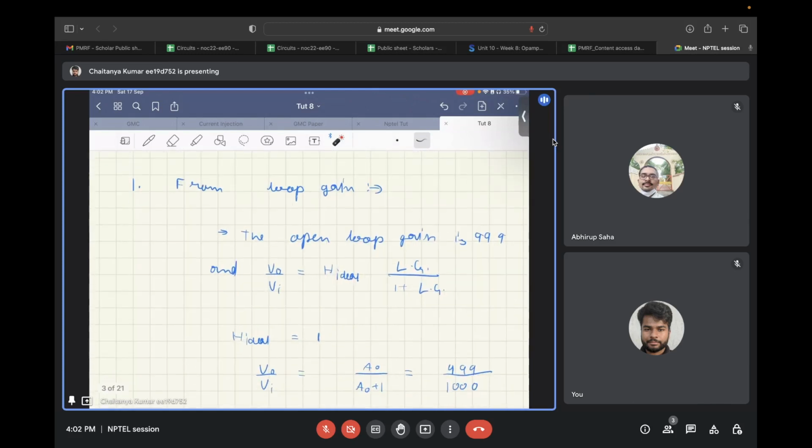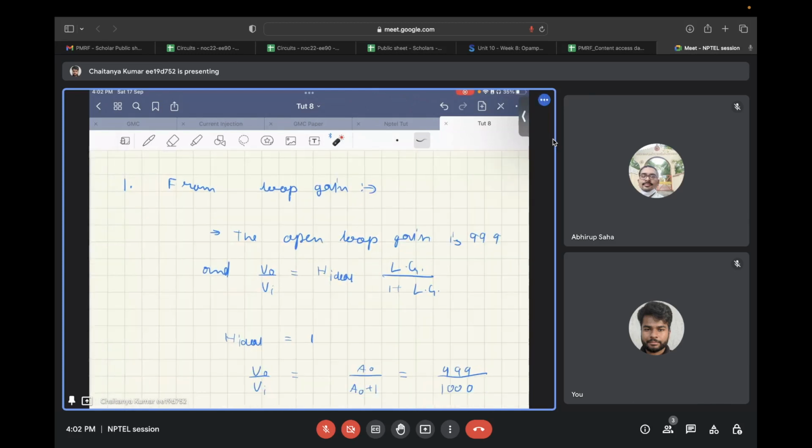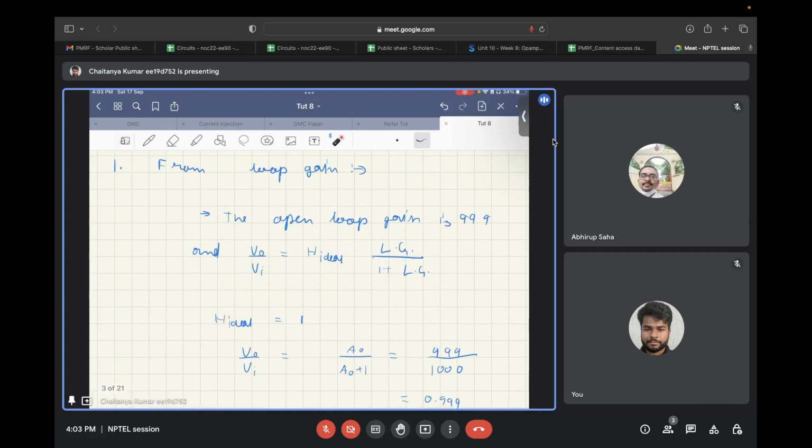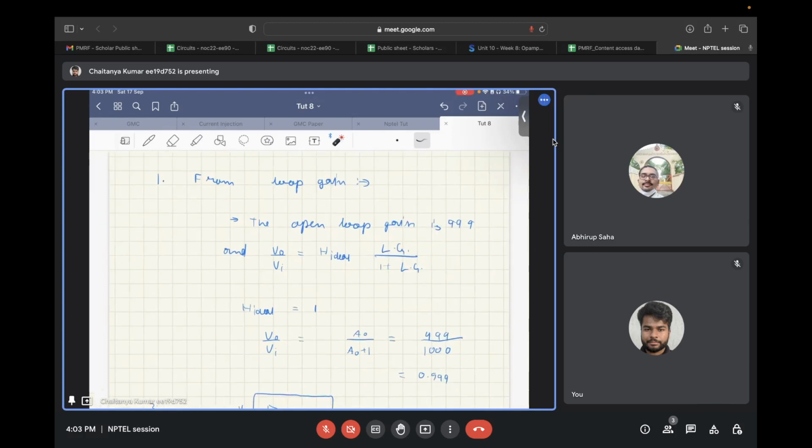Now, in circuits with negative feedback, the actual gain with non-infinite open loop gain is given by this formula. Whatever the ideal gain is, that is multiplied by the loop gain upon 1 plus loop gain. And the open loop gain in this case, as this is unity feedback...